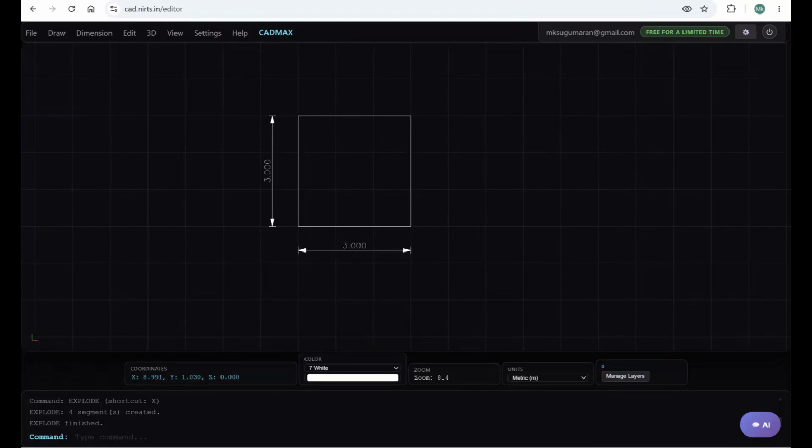In this tutorial video, I will demonstrate how to develop a structural model in an easy way. First, I draw a square using the line command from 3,0 to 0,3 to -3,0 and close. I dimension this in the X and Y direction using the dim command, selecting endpoints and the location of the dimension line. You see this drawing.